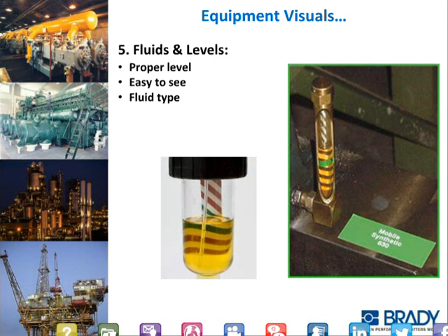The striped card in there, I call it a zebra card because it looks like a zebra. But you notice, with a simple principle of physics and light, where there's a fluid there, it turns those stripes to different angles and different widths. It turns that cylinder into a magnifying glass. So you can see off to the right, the Mobil synthetic label there tells me the type of lube. You can see the sight glass in there with a zebra card.